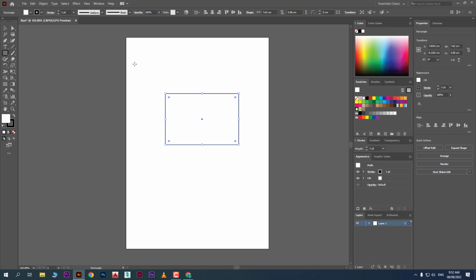You can design manually as well. You can click and draw like this. Now if you want to resize it, look at here on property bar. So here you have width and here you have also the height. So width you can change from here. All right. If you want to change the width of the rectangle, you can change from here. If you want to change height, you can change height from here. Or come to property panel, from here also width and height.